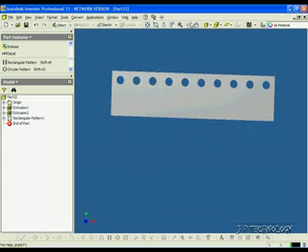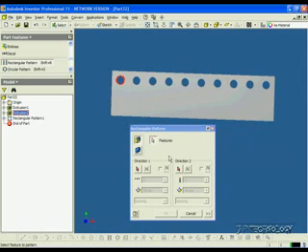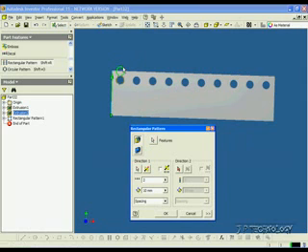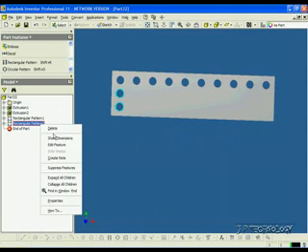Now you can also do it along another edge, so let's click rectangular pattern. Let's choose the feature, so click extrusion 2. This time for the direction, let's make it going down. Now it's going in the wrong direction right now, so we have to flip the direction by clicking this. And let's make 3 of them, and they'll be 15 millimeters apart. Click OK, and now we've cut 3 going down that line. Now let's delete these 2 patterns that we just made.